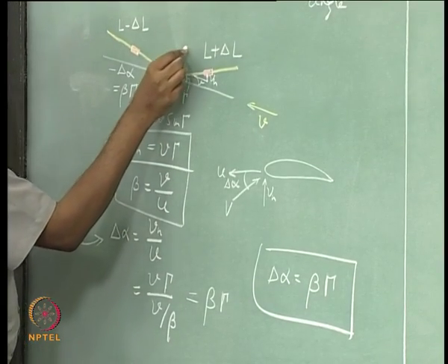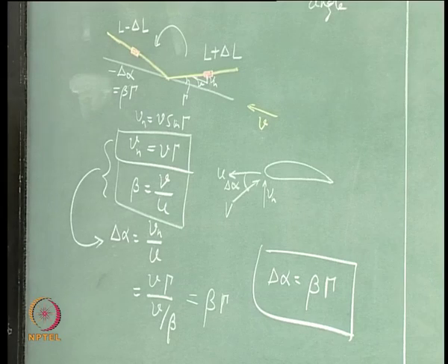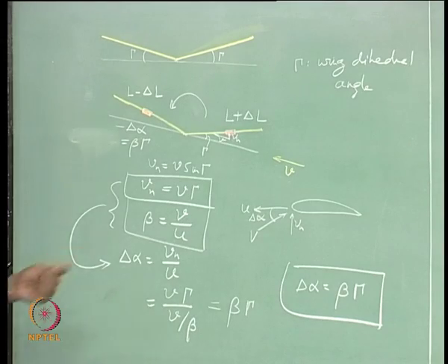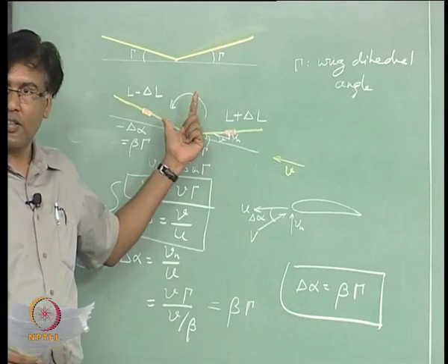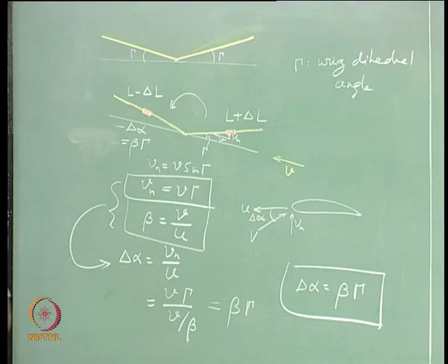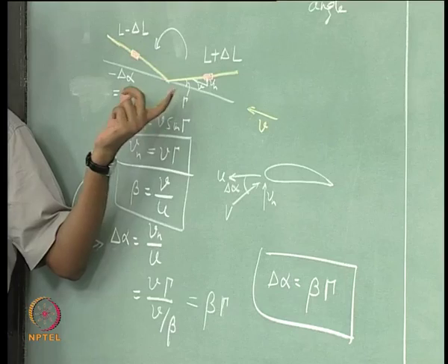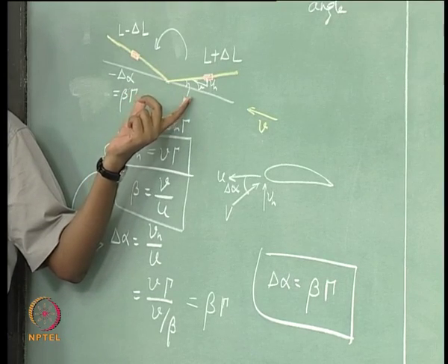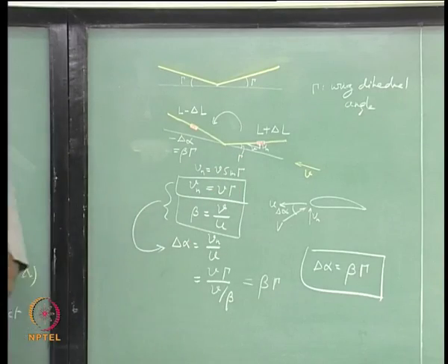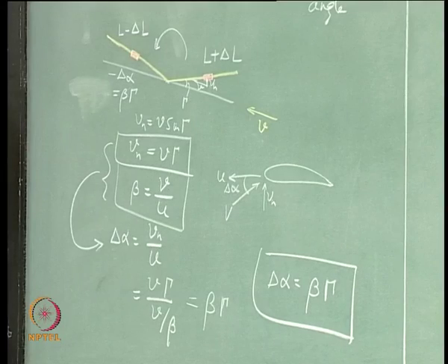And that is going to give me a moment which is negative. So, a positive side slip has given me a negative rolling moment, only when I have wing dihedral, and this is for positive dihedral. For negative dihedral we use a word called anhedral.